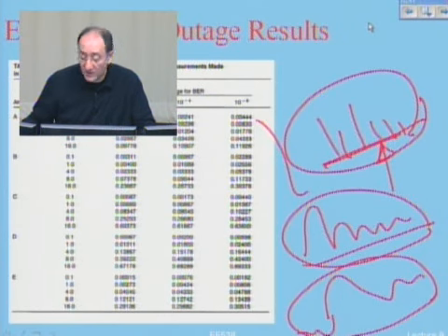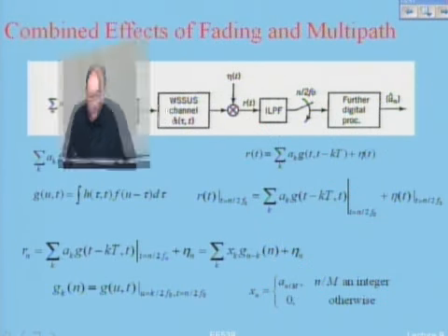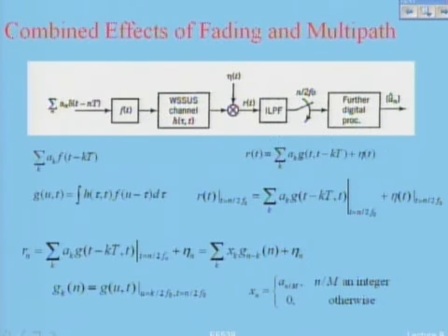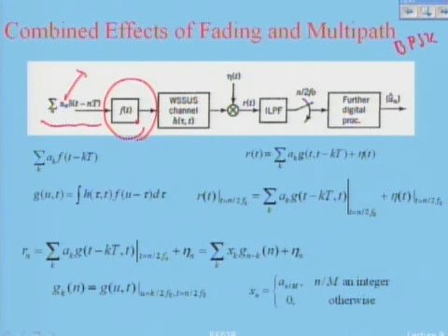To be more specific on that, let me come in here. This is the famous figure 1 for all the communication systems. I have a pulse shaping filter. This is a baseband transmission. I have a bunch of impulses coming inside, and these are my transmitted pulses. Assume I have binary PSK, a simple thing. If it is binary PSK, A sub n is plus minus 1. So I have these pulses which have positive and negative polarity, and the shape of these pulses is f of t. They pass through a channel.